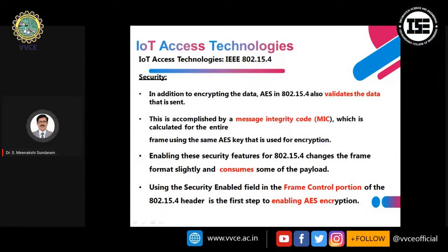And in addition to the encrypting of the data, AES validates the data that is sent, and this is accomplished by a message integrity code, MIC, which is calculated for the entire frame. Enabling the security features for 802.15.4 changes the frame format slightly and consumes more payload.